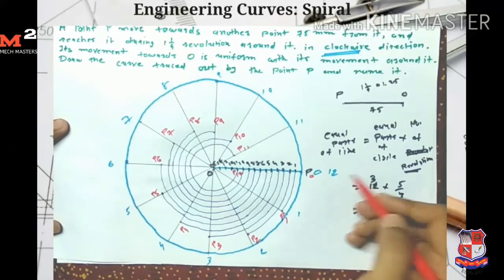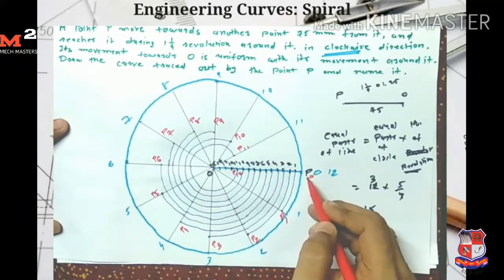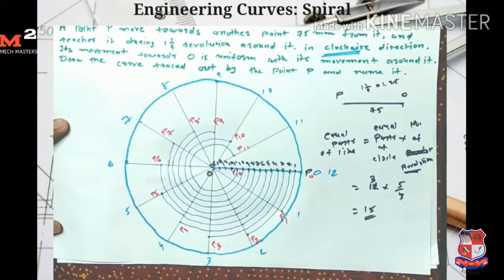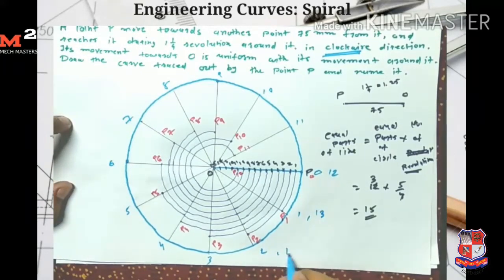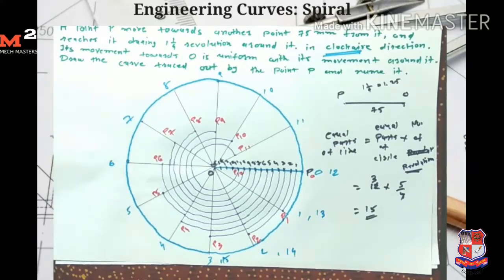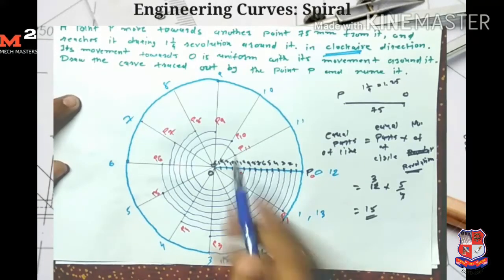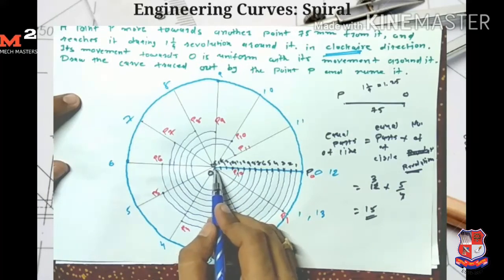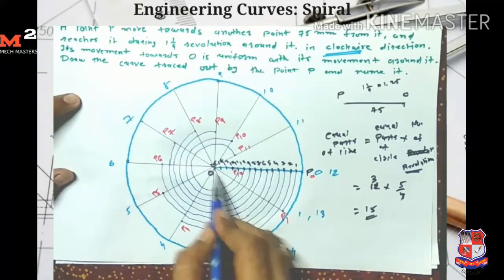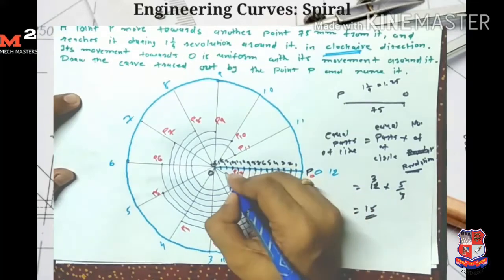But we divide the line into 15 equal parts, so we continue numbering in this direction. So here 13, 14 and 15. Now I take O13 as a radius, and O as a center, draw another arc which intersects the line O13 here.